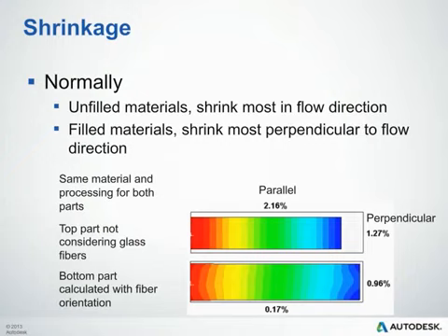This is because plastics typically have a tendency to try to return to a stress-free state. So when you injection mold at our injection location on the left here, we're stretching out these strings of spaghetti, or these long polymer chains, and they just want to return back to their normal shape or their stress-free state.